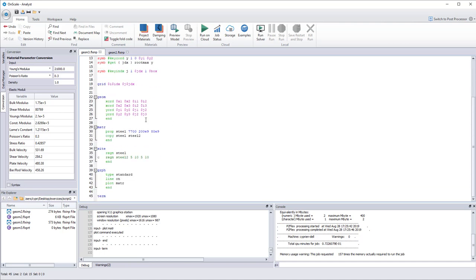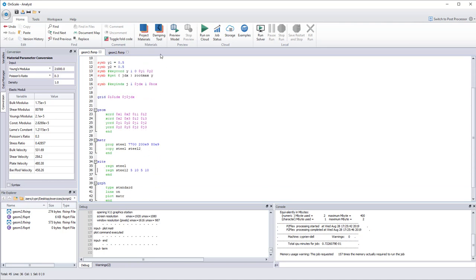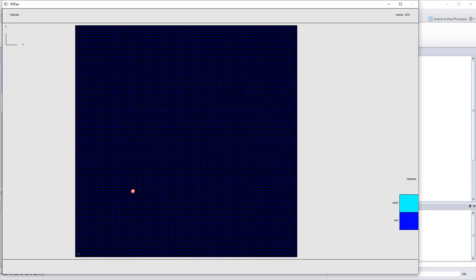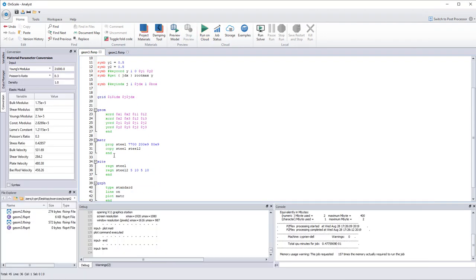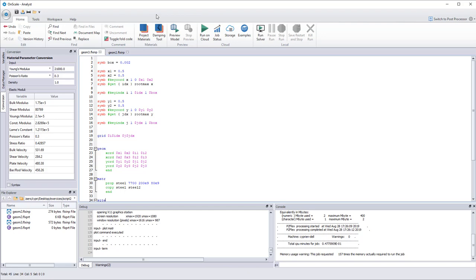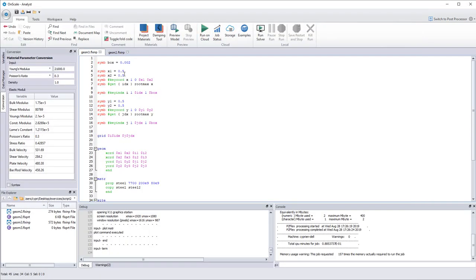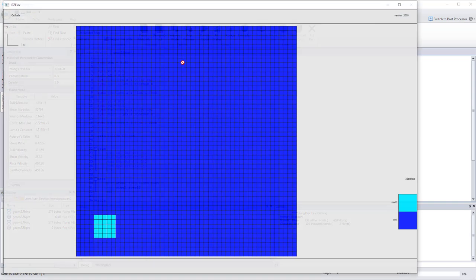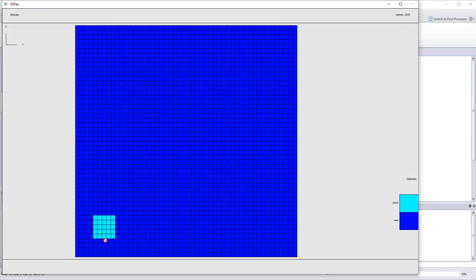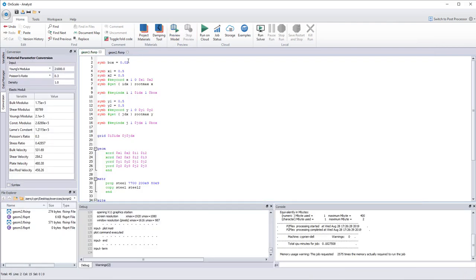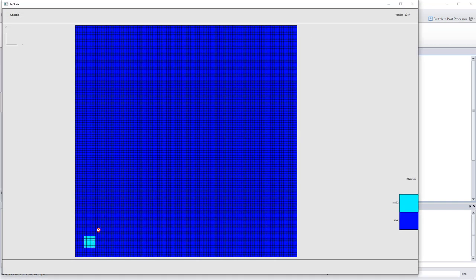Now you saw that my region here has been defined by directly specifying the nodes. So there's a problem by doing it like that. When I change the mesh size, sorry, I didn't save, I think. Yeah, it's here. Okay, very, very small. Almost cannot see it. Sure. Let's put 0.02. So the problem is here for 0.02 box size, my position will be here because I'm fixing those nodes. But if I change the mesh to 0.01, then you see the box moves. So the region actually is not fixed.